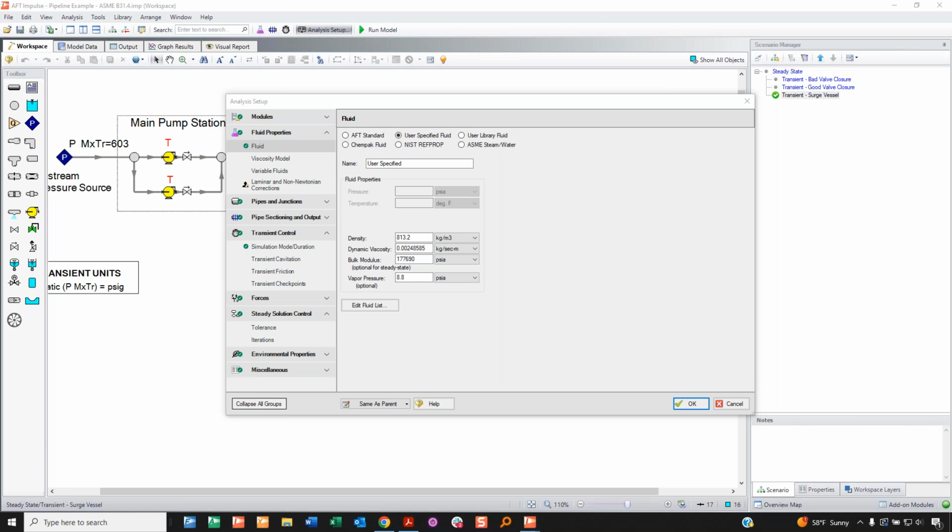So we can look at things like air valves, but it is a very touchy subject where you have to understand that we still do the math assuming all the pipes are full of liquid. It's a theoretical, this is how much air would be coming into the system, but we're not actually modeling it. It's not a two-phase solver. So when you are priming a system, we are not looking at the moving boundary of that liquid displacing the gas. That's what it comes down to.